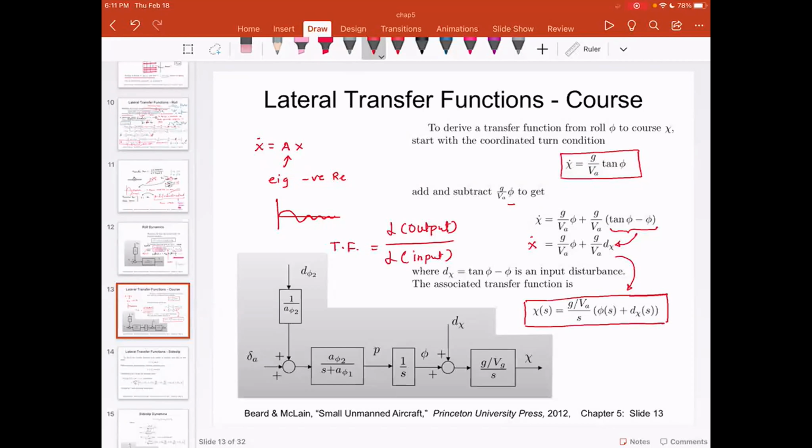And some of you may ask me, why is this jugglery needed? Is this jugglery really needed? The answer to that question is no. If you can deal with the original nonlinear equations in state space dynamics, you don't have to deal with this. But sometimes the linear approximation is preferred because it's easier, it's quicker, and it will give you a good insight into the eigenvalues and the system behavior. So what we are trying to do is come up with a linear approximation to this super complicated nonlinear equation.